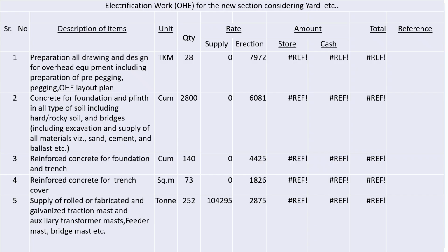But according to the changes of cantilever and the load, and for the anchoring mast and the ATD mast, your mast size will change because of more load. For an anchor mast in 25 kV OHE you can use B175 or B200 according to your load.